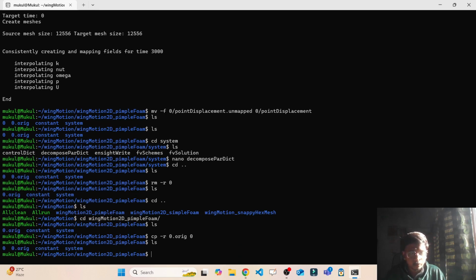Yeah, so one tip for you all, in between the videos I am giving some tips also. OpenFOAM will not read 0.org. You have to copy the files of 0.org to a 0 directory.